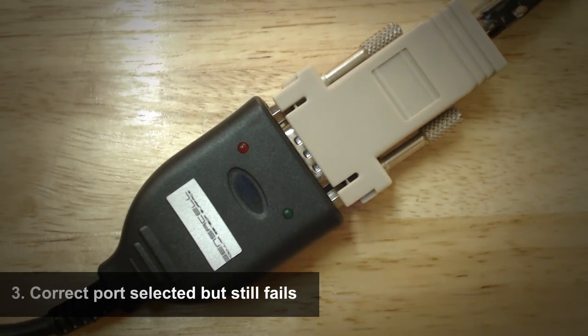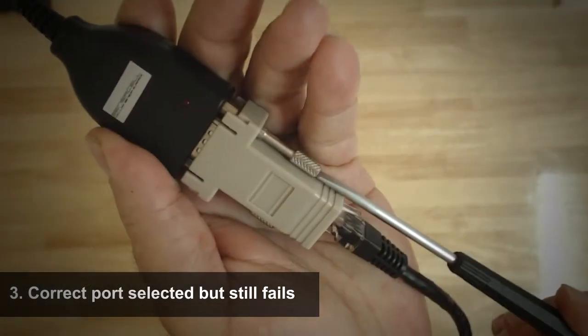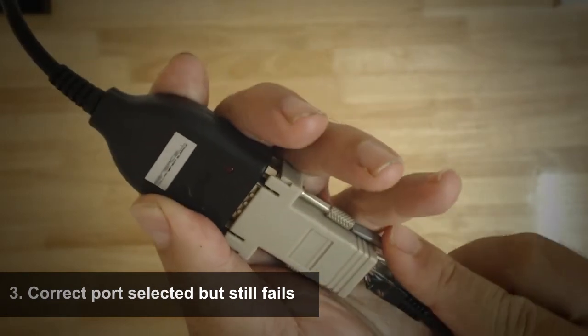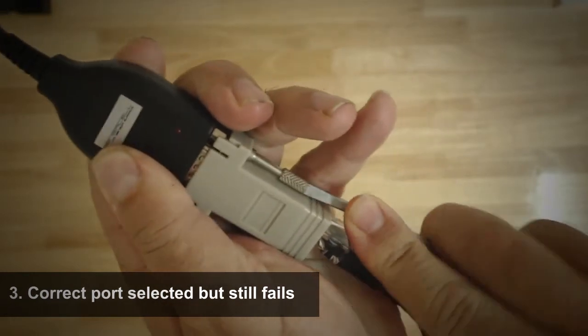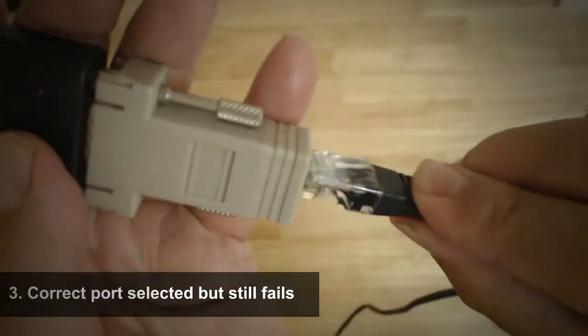If you are sending data but not receiving data, in other words the panel is not responding, then first check the connection from the USB adapter to the panel. Try to connect to another module or to another open port on the same module. Also check the cable integrity. Make sure that the connector adapter is firmly attached to the DB9 terminal on the one end and the RJ45 jack is securely seated on the other.